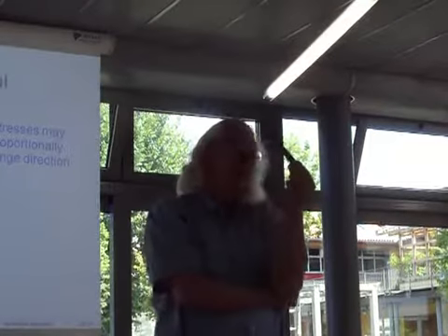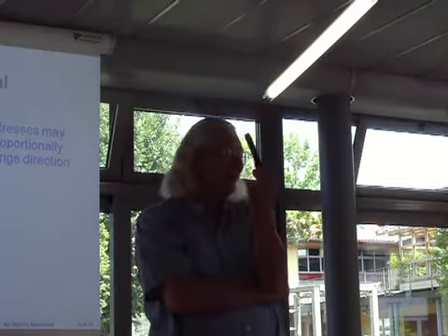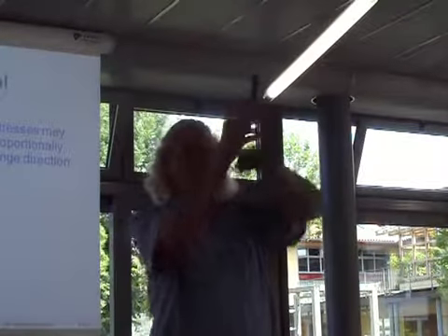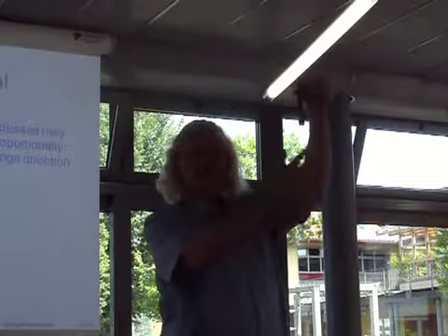So it's a non-proportional loading. And this is the problem with people who only look at the math. If you only look at the equations, then, oh, this is a very non-proportional case. The principal stress direction changes from this direction to this direction. But if you ask anybody who's been in the lab, oh, this is a simple uniaxial loading.